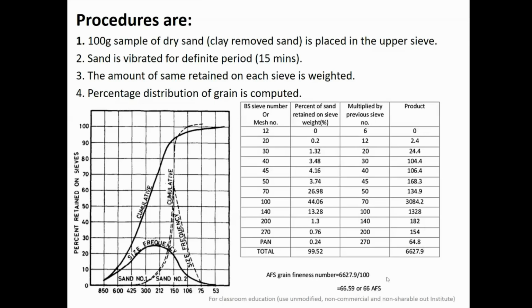This will give you an idea about the average particle size of my sand sample. So this is a very easy process. You just require a mechanical sieve and a shaker.